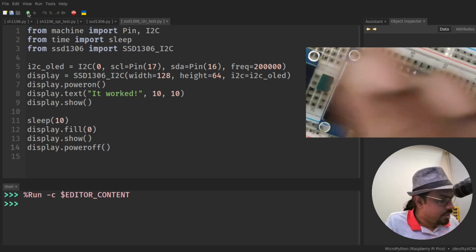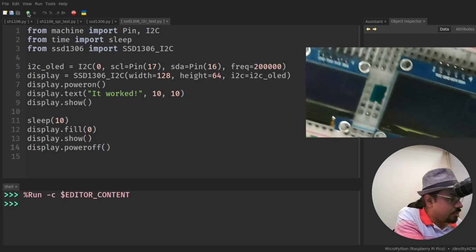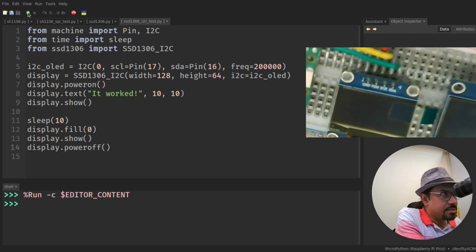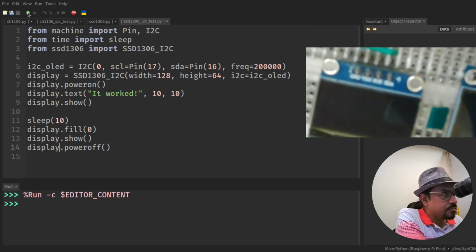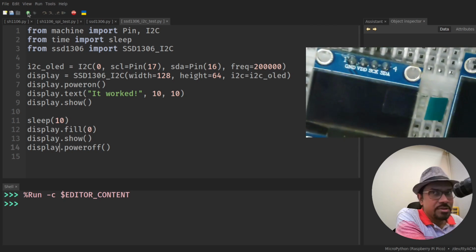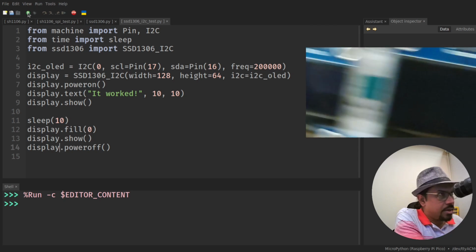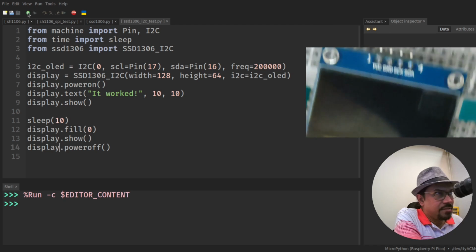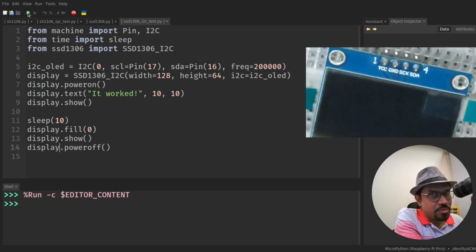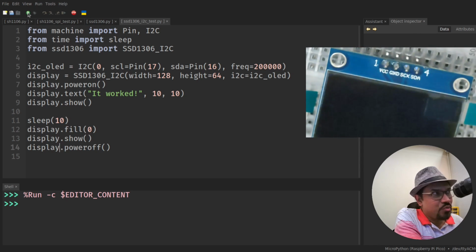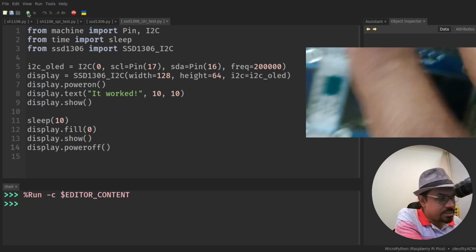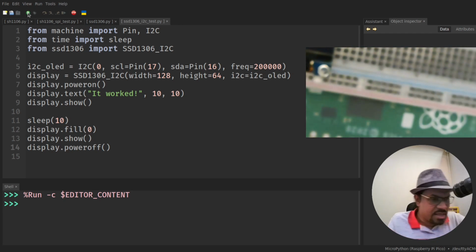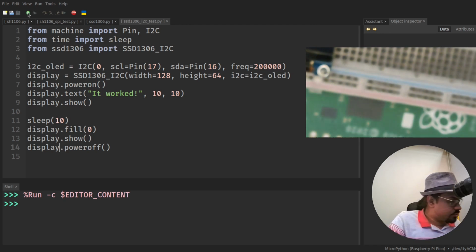It's exactly the same. The only thing to note is the VCC and the ground connection. In this display, as you can see, the first pin is ground, the second pin is VCC. But on this display, however, the first pin is VCC, second pin is ground. So you should be a little careful about the wiring. So make sure you wire it up accordingly. The wiring might change here and there. But this is based on SH1106. I have that, I think, connected on one of these boards. So I'm just going to plug this all in this board and I'm going to show you.